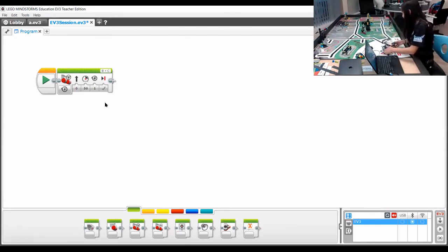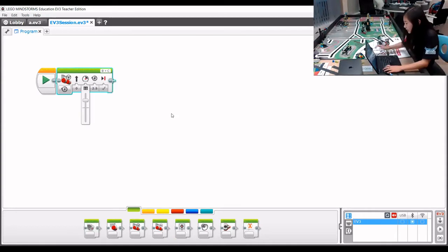So you can run your robot through and see how many rotations it takes to get all the way to the slide. Here it's going to take about 2.5, so we're going to try that first. It's still going forward, and we'll change the number of rotations to 2.5. We'll also reduce the speed so that it's a little bit slow.